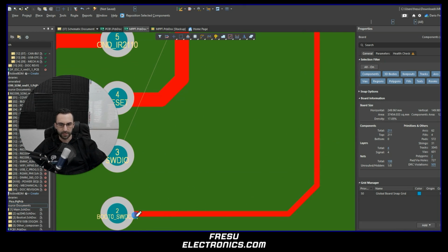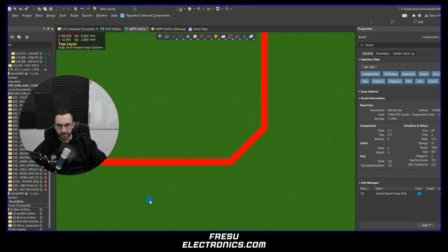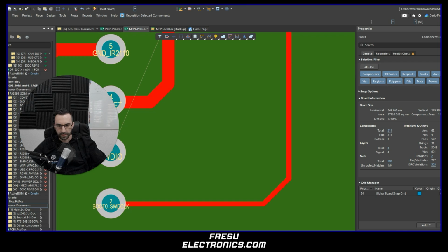You can see that if we have a 1 gigahertz signal, the return current will flow back under the trace in this return reference plane, in this big return reference plane. But when we have a 10 kilohertz signal, then the current will start to spread much more.